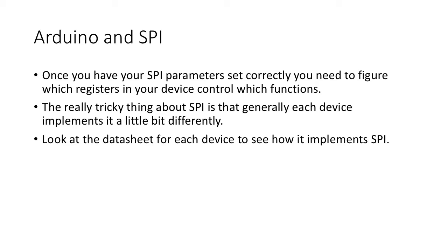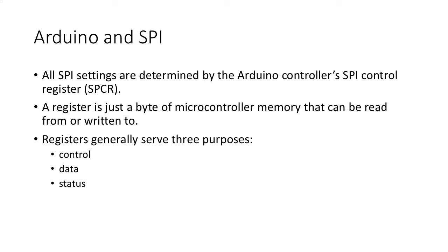And so you've got to read data sheets, and sometimes you won't find data sheets, in which case you have to sit there and test which pin goes to which pin on the chip. And you may do that with a continuity tester or with simple inspection and tracing of the board traces.